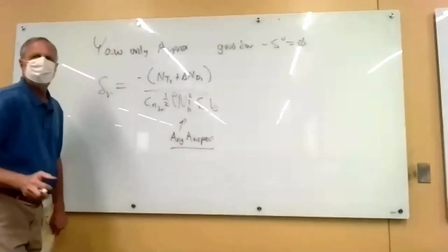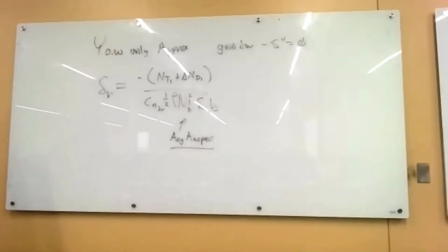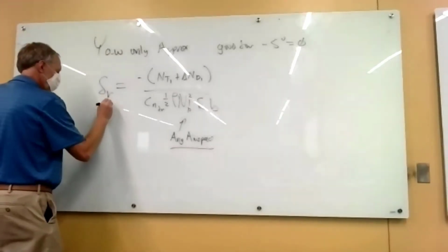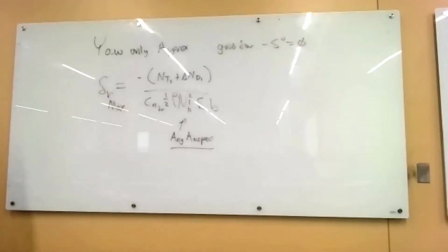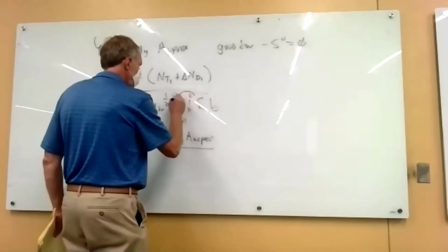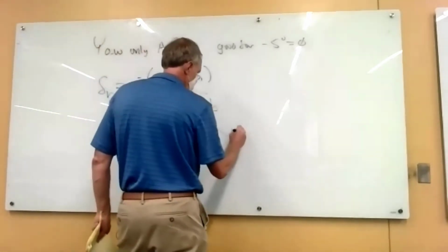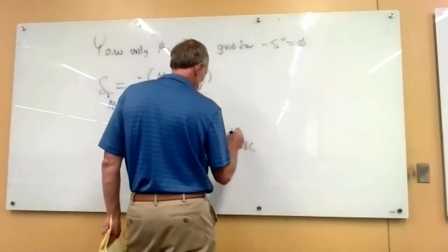But I said, how slow can you go and still control the airplane? That's going to be determined by the maximum rudder deflection that you can get from the airplane. Rudder pedal full in, the rudder's over against its hinge limits, its mechanical limits. And that is what we call the minimum control speed.